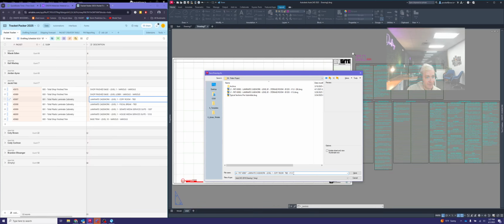And then if we ever had a revision in-house, like if I had a correction for you on your list, you would change this again to version 1.1, then version 1.2 if there were multiples. If there was a correction from the architect, as in there's a red line, or the architect had revised their drawing and affected your print, then you're going to change this first number to 2.0 or 3.0 and so on. First draft is always version 1.0 though.